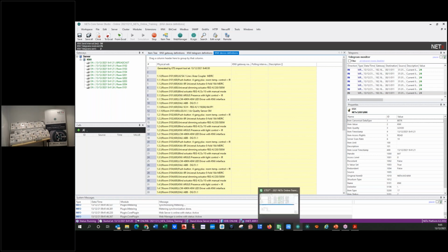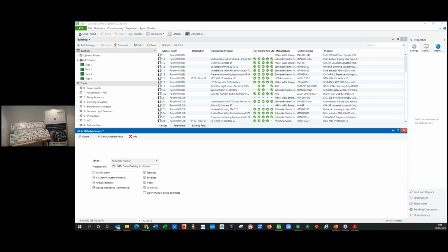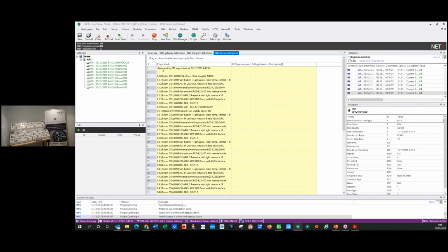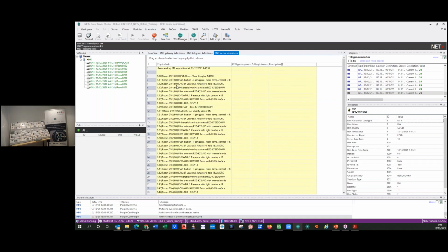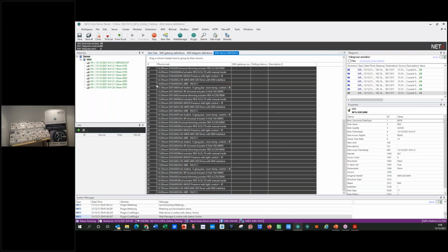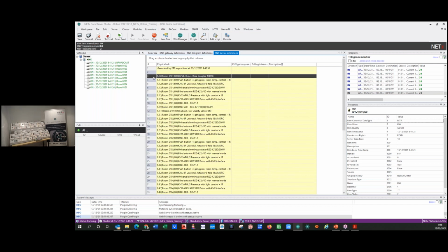And this is one thing that was mentioned here. If you take a look in the ETS, the option device monitoring, it was telling us commented, because these definitions at the end, and this is also important to understand, these definitions at the end make you spend data points for your license. So if you are interested in knowing all these elements, you have several, 58 or 59 physical addresses, okay? This is 59 data points that you need to invest, that you need to waste for the license. Okay, so the license is using 59 data points to monitor the physical addresses.